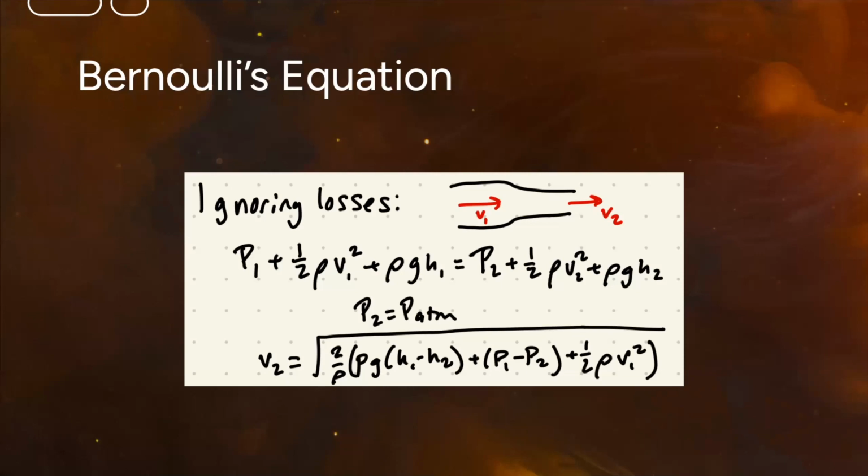So all these factors impact the velocity of the stream exiting. Specifically, it is parabolically shaped to minimize vortices due to the gently sloping sides of the nozzle. The fluid flow stays as laminar as possible by ensuring that there are no sharp geometries that the fluid can get stuck on, so the boundary layers are minimized.